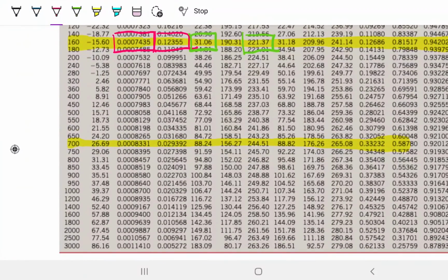My question is, where is my number of 0.04985? Does it fall between these two guys here? Is it greater than this guy here, or is it smaller than this guy here? Well, it's definitely greater than this one, and it's greater than this one here. So that indicates to me that this is not a saturated mixture. This has to be a superheated fluid, right?